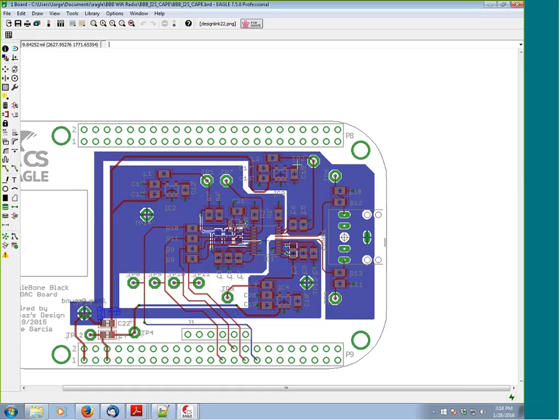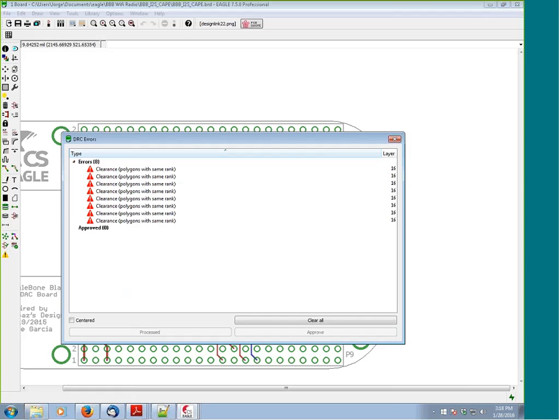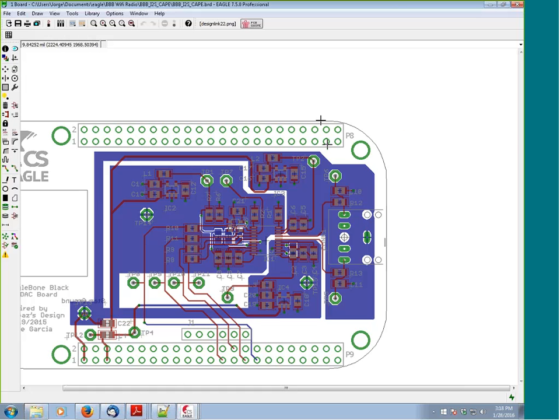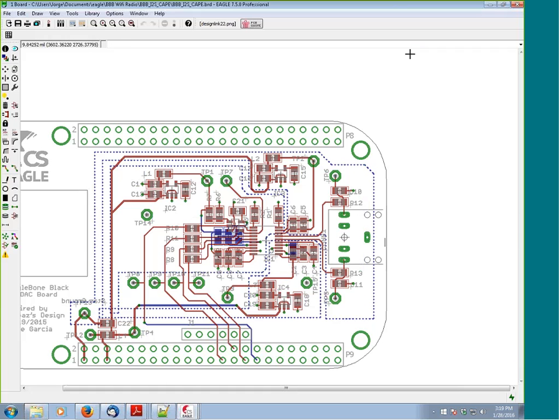So sure. And my last question is that whenever I click on the ratsnest command that basically fills the ground for every area I've selected, I don't know how to undo that unless I click and delete on it. Is there any command that can undo the ratsnest? Yes, there is. Let me go ahead and show you that. This should be a shortcut, and I actually have it as a shortcut, but I'll show you right now. Basically, the command to undo the polygons is ripup, space, @ symbol, semicolon. Hit enter, and they go back.